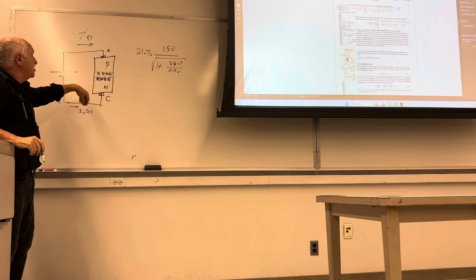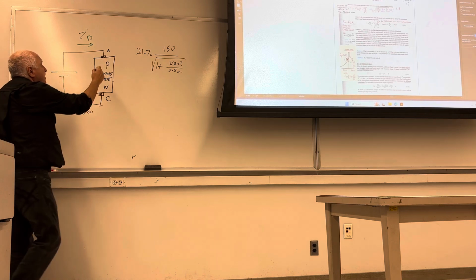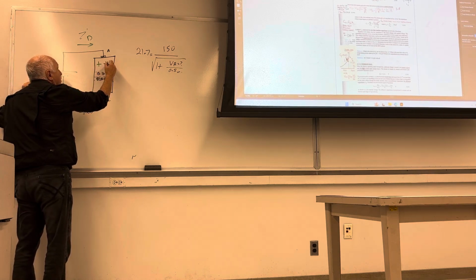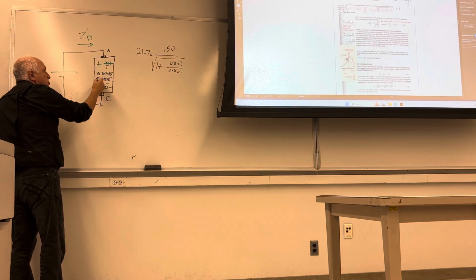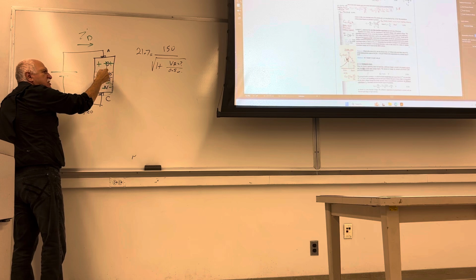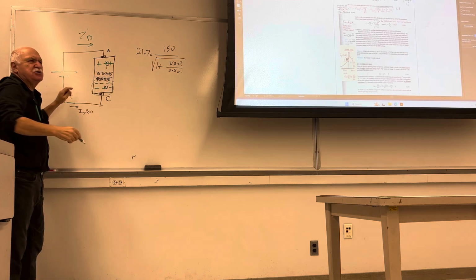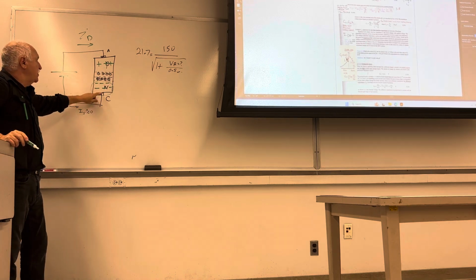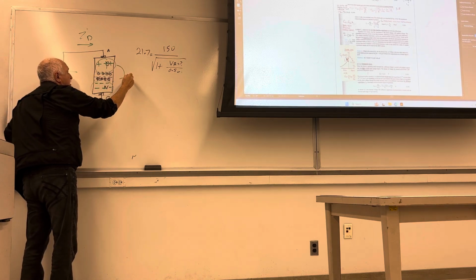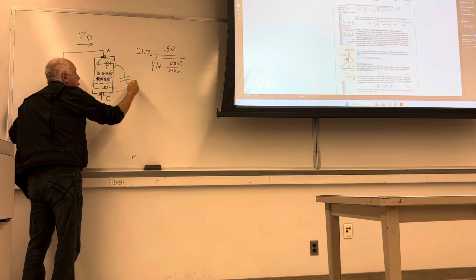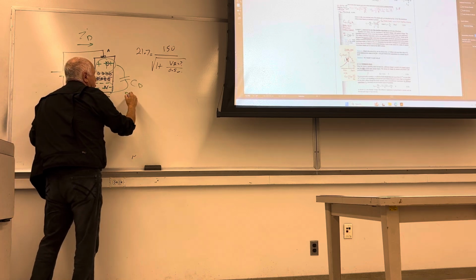The more positive you make that, a greater charge will pile up in this region, in the neutral region, so-called, in addition to what is inside. But the inside capacitance will be so minimal compared to this one, the larger one. This produces a capacitance called CD, diffusion capacitance.